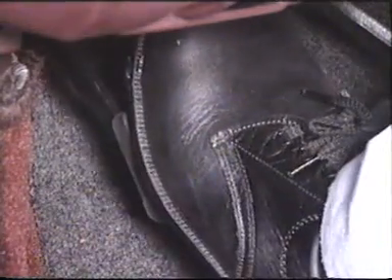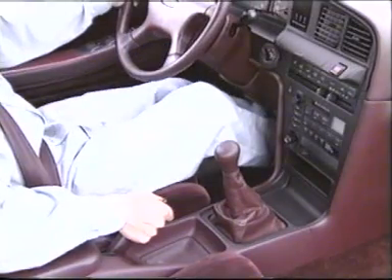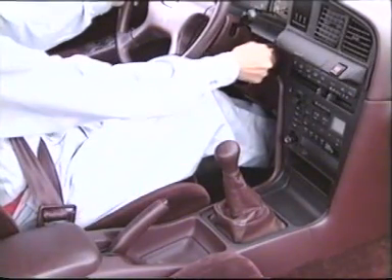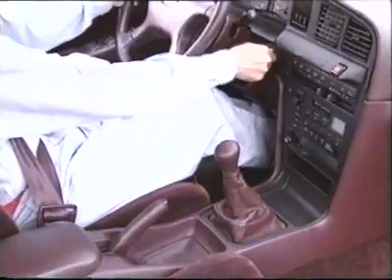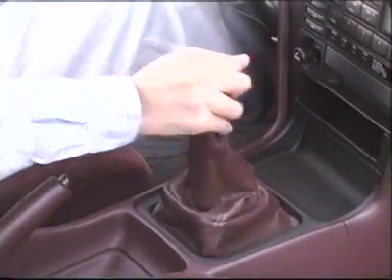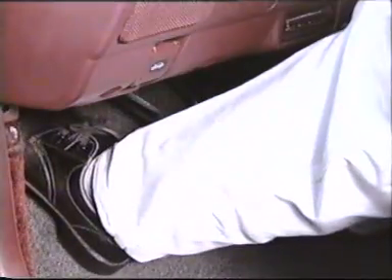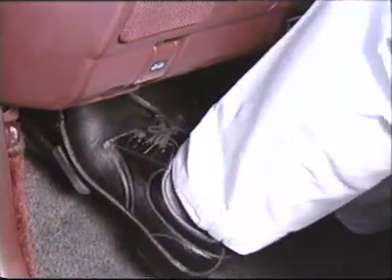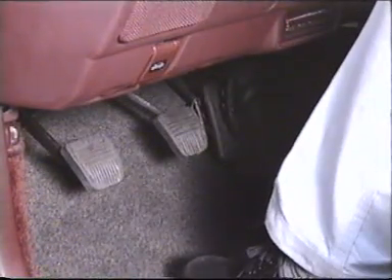Unusual sounds or noises may be heard from the clutch when it is depressed or released. Put stoppers under the wheels, depress the clutch pedal and start the engine. Put the shift lever in the neutral position and release the clutch pedal. Depress the clutch pedal again.